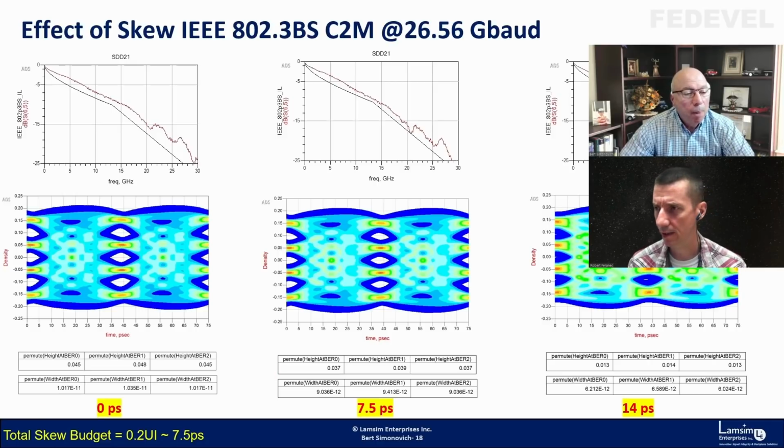How did you come up with this red line? The red line is a measurement of your channel. It's the combination of the plus and minus signals, from one chip to the other, basically. So that's the whole length of your routed trace on your board. That's the loss of your trace, really.